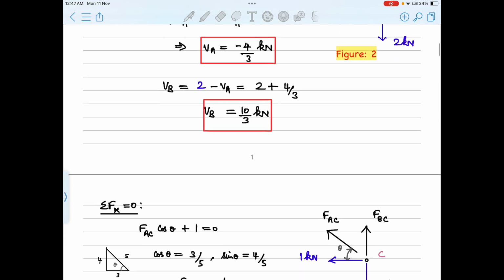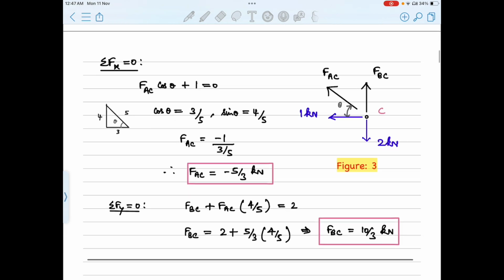We have the member forces to be determined there. If we use the two equilibrium equations applicable at joint C, it's a cakewalk. The joint C is shown in figure 3 with relevant details. Once we determine these two member forces such as FAC and FBC, we are done with solving for all unknown forces as this truss is a determinate one. This is how we solve a problem by force method.